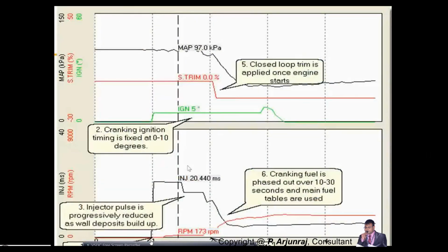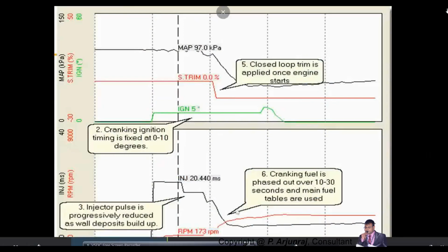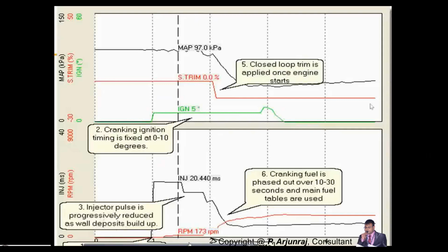This software will also help you to find out the injection timing and also the injection quantity. In case you want to increase the fuel quantity, or increase the timings, you can also take corrective actions according to the inputs you receive with the help of the software, the tool called the calibration tool.